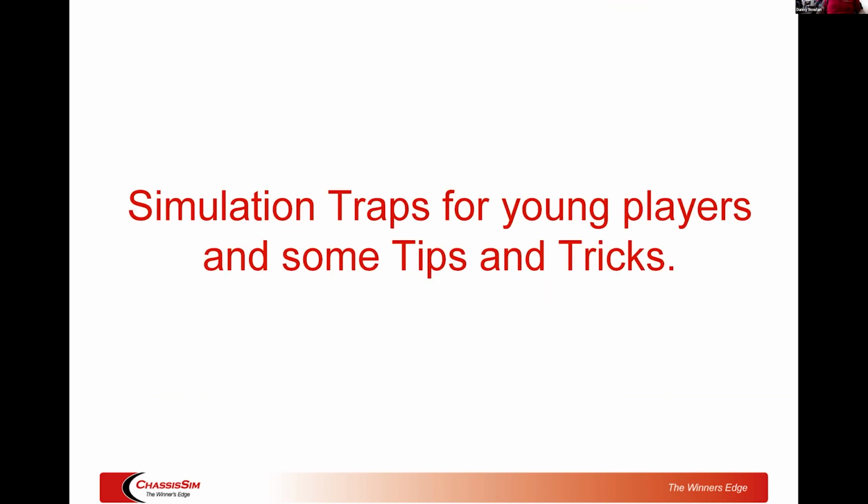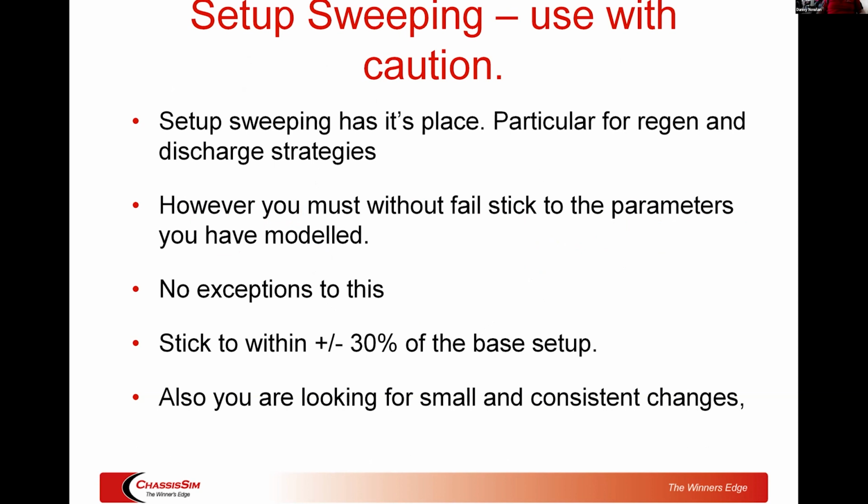Okay, simulation traps for young players and some tips and tricks. First things first, setup sweeping. Use this with extreme caution. Now, don't get me wrong, setup sweeping has its place, but the big trap that I see young engineers fall into, and I see the big end of town, like F1, NASCAR, IndyCar, and factory LMP1 fall into, is that they over-rely on setup sweeping. Here's the thing, you've got to stick with the parameters that you've modeled, and you always stick to within plus or minus 30% of your base setup. Anything beyond that, you're just guessing. So really keep that in mind.